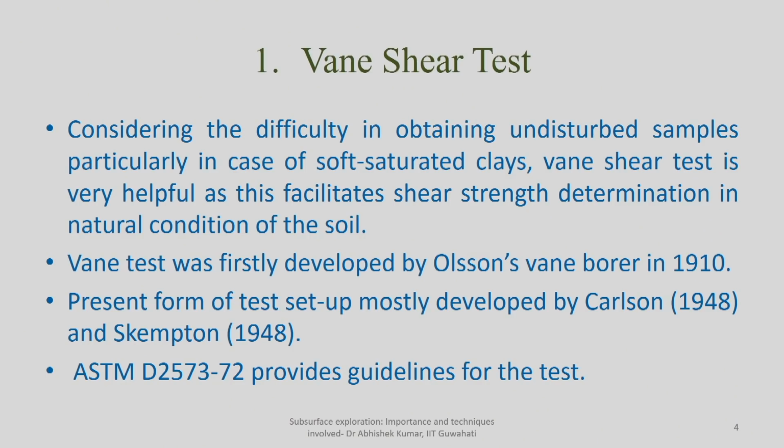So it is a very challenging task to collect an undisturbed soil sample in case of soft saturated clays, partially because of disturbance, partially because of change in moisture content. So in such cases, when we have this kind of soil at the site of interest, the vane shear test can be very helpful, as it facilitates in situ determination of shear strength.